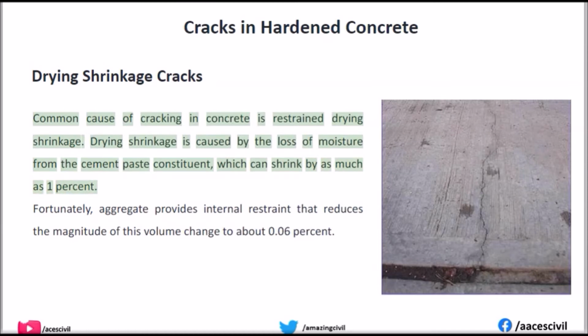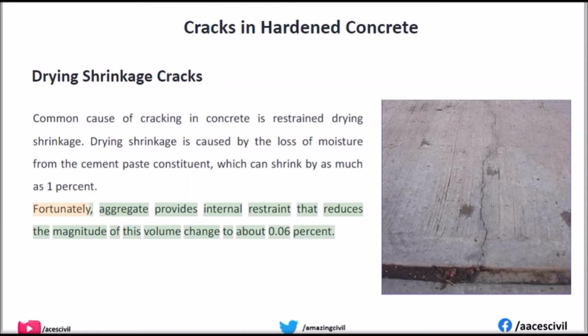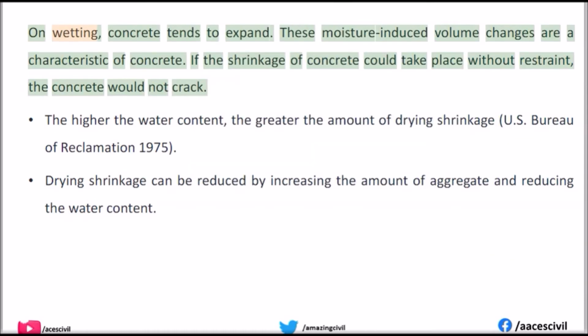Fortunately, aggregate provides internal restraint that reduces the magnitude of this volume change to about 0.06%. On wetting, concrete tends to expand. These moisture-induced volume changes are a characteristic of concrete.